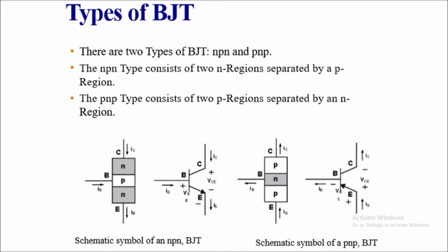In this NPN, the currents appear here. In NPN we have the outgoing current from E, so the arrow is pointing outward. And here are the voltages across the NPN. We have VBE, which is the voltage between the base and emitter, and VCE, which is the voltage between the collector and the emitter. There is also another voltage, the BC voltage, or the base to collector voltage. We reverse things with PNP, and the diagram shows that.